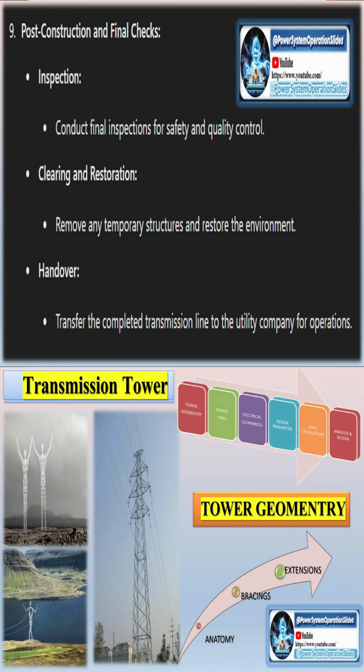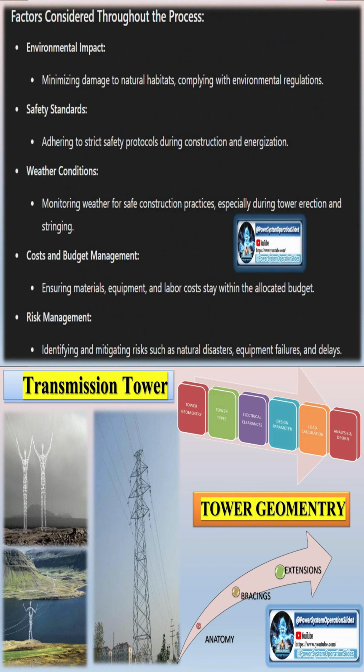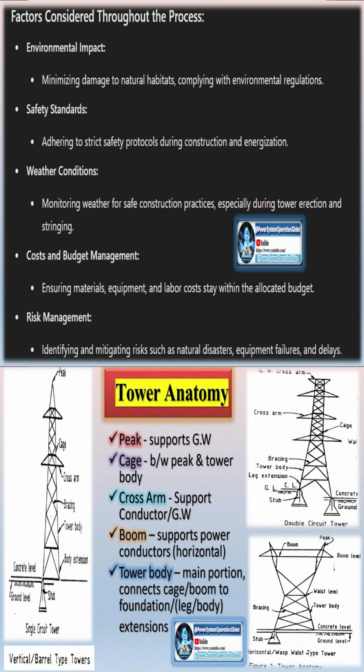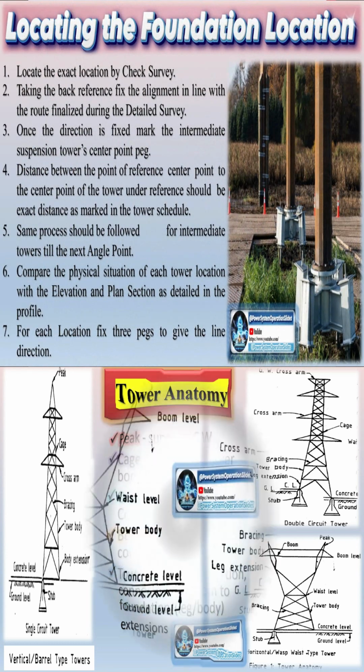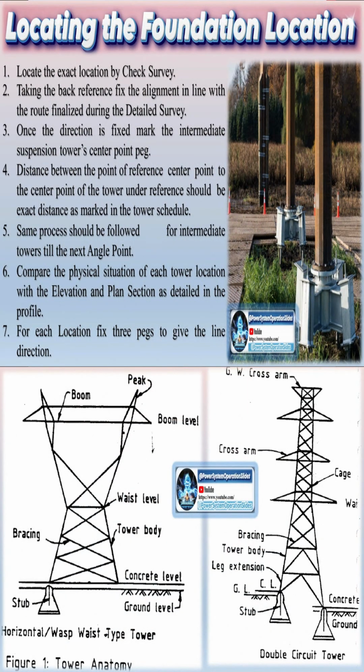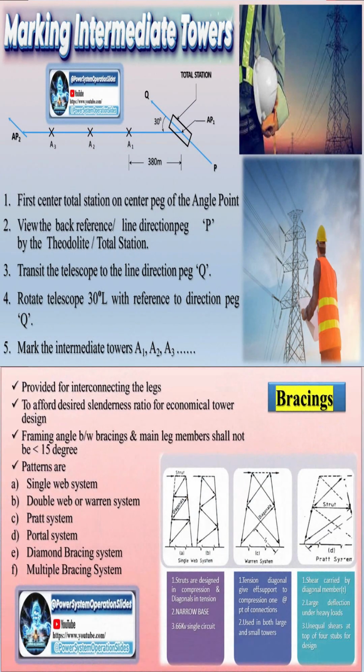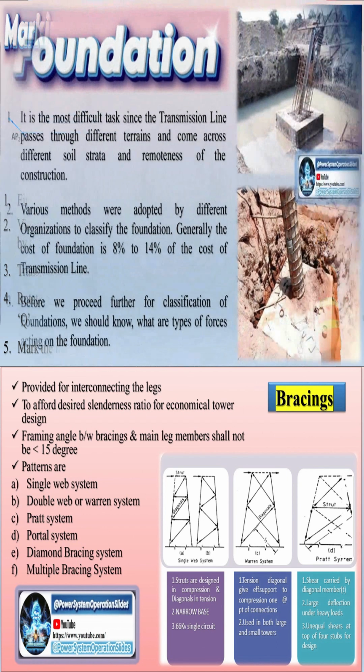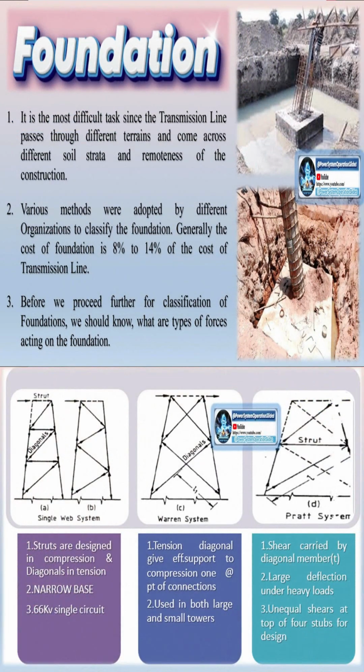The proposed transmission line route must avoid or minimize interference with environmentally sensitive areas such as wetlands, wildlife habitats, national parks, and conservation zones. Additionally, densely populated urban areas should be bypassed to prevent disruptions to communities, reduce potential legal disputes, and avoid costly compensation for land acquisition.